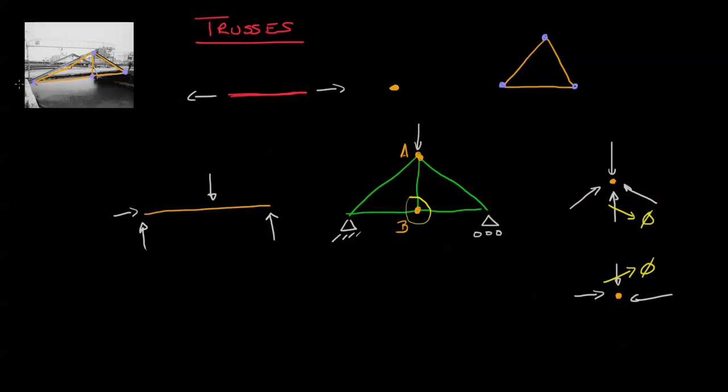Now, that said, you might ask, well, what's the point of that even being there? Those of you who are careful also ask, well, that may be, but Brett, when they're using the bridge, the force isn't applied up there. The force is applied at the bottom, and in fact, those arrows are somewhat misleading because of the way a bridge is built. The force is applied here, here, and here. As a truck goes over, the forces are concentrated only at the pins. And we'll talk about that in a minute or two.